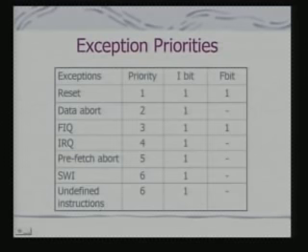So these are not really interrupts, interrupts being explicitly generated to interrupt your current flow of execution. When we refer to interrupts explicitly, we shall be referring to FIQ, IRQ and software interrupts. Others are exceptions, and everything put together is actually exceptions. Interrupts are also exceptions.